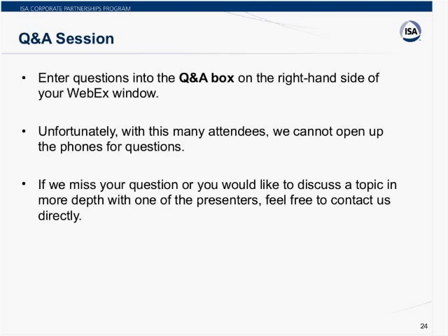Again, my short answer would be I would recommend doing an FEL2 and comparing brand X and Y from both angles: what would the cost be to rip out brand X and put in brand Y, and look at the long-term benefits and cost to that, and weigh those out from a return on investment standpoint. If brand X is a 20-year-old DCS and it's nearing obsolescence anyway, then that's one scenario. If brand X is a fairly new DCS that was put in 5 years ago, that's going to be a much harder hill to climb from a justification standpoint. That being said, we have seen some cases where decisions are made at a corporate level to standardize, and that's what's going to happen. So those would be some of the variables.